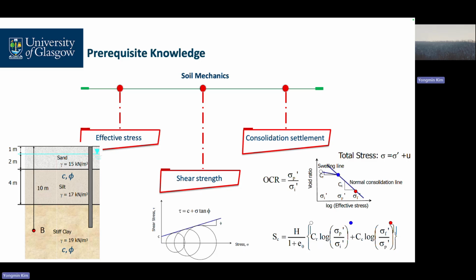That's why we are able to calculate effective stress. This is 3 meters, right? And then unit weight is 15 kilonewton per cubic meter times depth. So this is 3 meters, the units cancel out, and then this unit becomes kilopascal. This amount of kilopascal pressure is confining our pile,